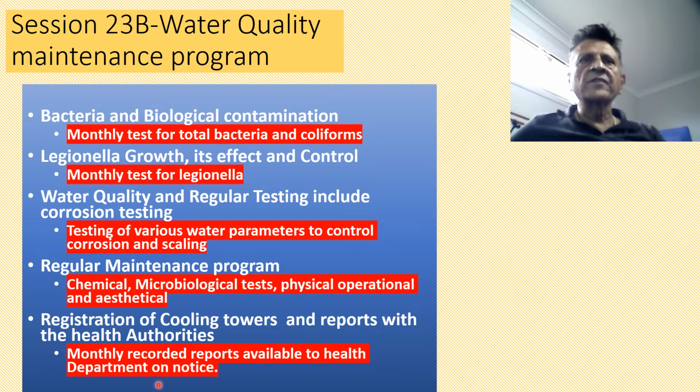So we need to have a regular maintenance program. And we have to have a monthly test of total bacteria, coliforms, to ensure that the water is in reasonably good biological status.